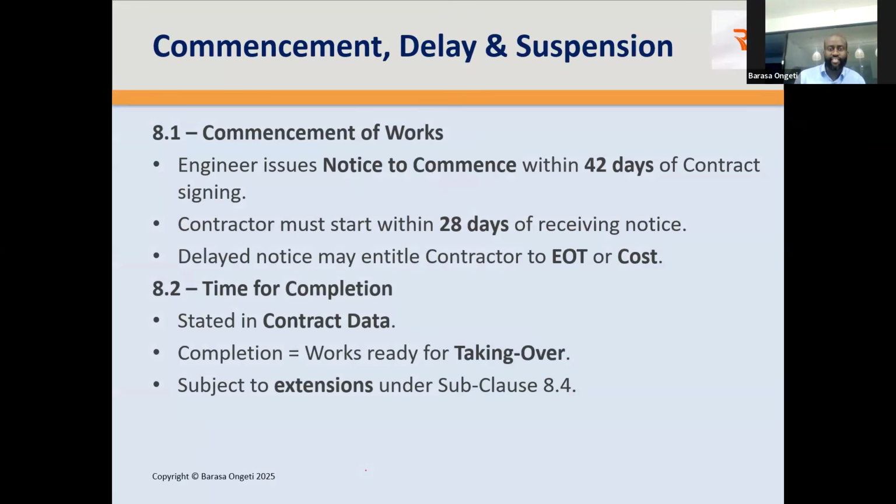I believe that answers the question that was raised by Titus Toom. Titus Toom said, what is the time difference between letter of acceptance and the commencement date? So within 42 days of letter of acceptance, which is usually issued upon signing of the contract, the engineer must issue the notice to commence. However, there's a caveat to that statement. If you read your contract, it's not a must that it's issued within the 42 days.